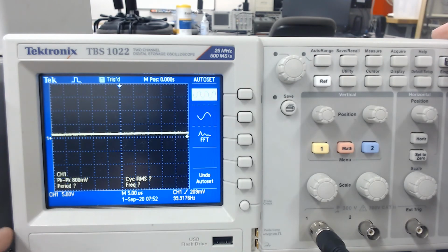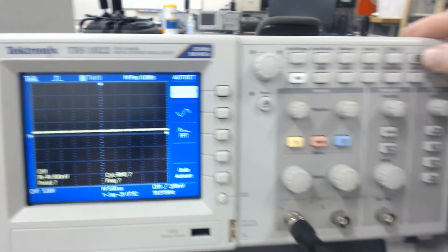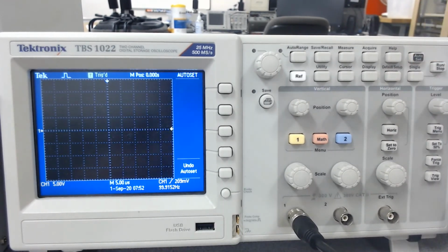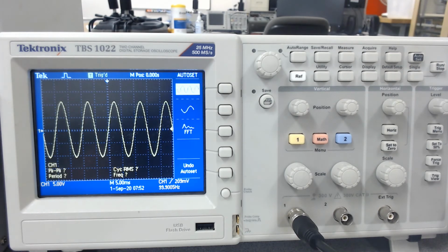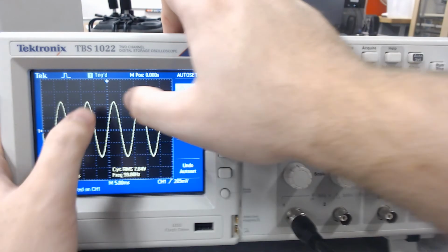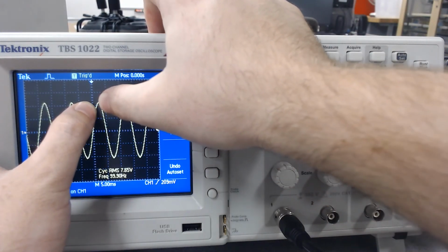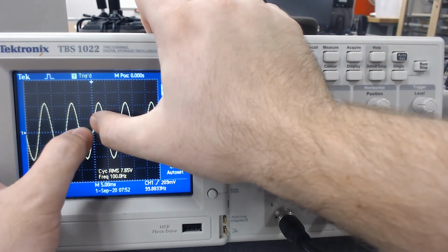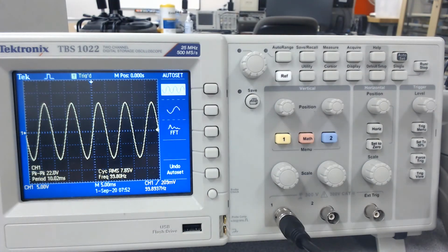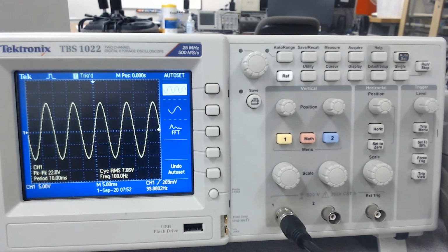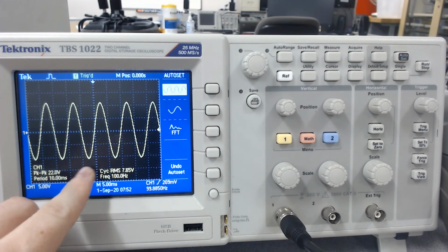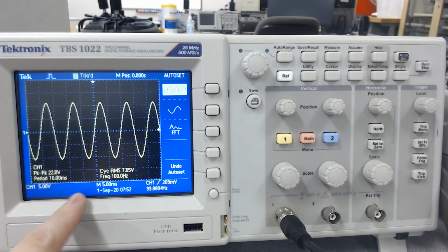So let me hit the auto set button and explain a little bit more what I'm talking about. So if you hit this auto set button, what we were really only seeing was this small little portion down here. Like it wasn't showing the full wave, and so it was only showing the change from one end to the other was 1 volt, as opposed to, we actually know, again, it's 22 volts.